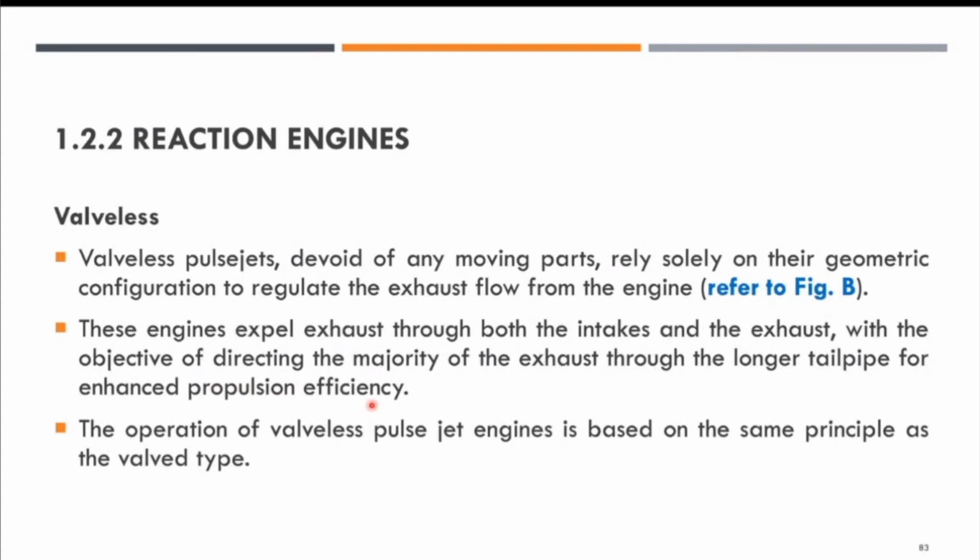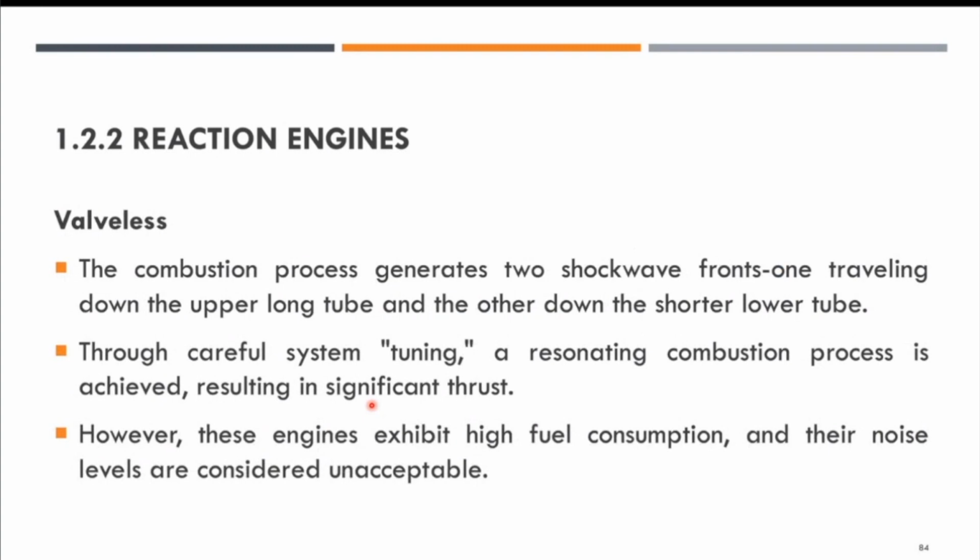All right. The combustion process generates two shock wave fronts, one traveling down the upper long tube and the other down the shorter lower tube. Right? So through careful tuning, a resonating combustion process is achieved, resulting in significant thrust. However, this engine exhibits high fuel consumption and its noise level is unacceptable.